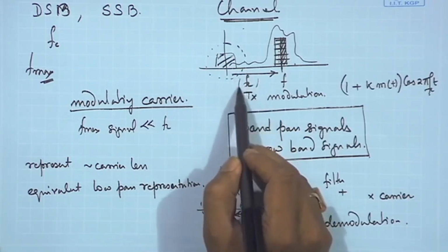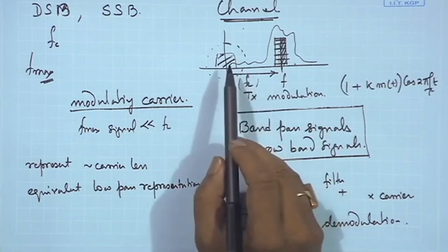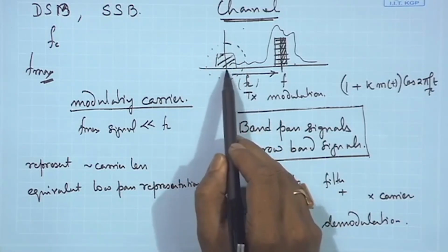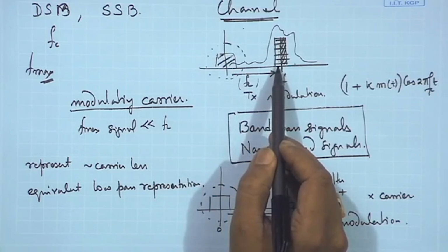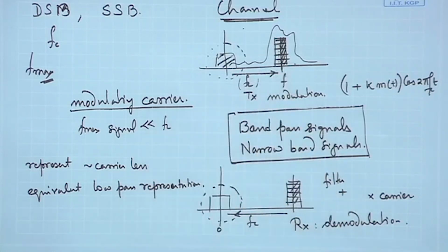And if we know this carrier frequency, then we can translate all the studies that we do in baseband to the corresponding effects of the passband. Or in other words, what we are going to establish soon is the relationship between the baseband or the low pass equivalent signal and that of the passband signal, so that we can do the studies in the equivalent low pass form.